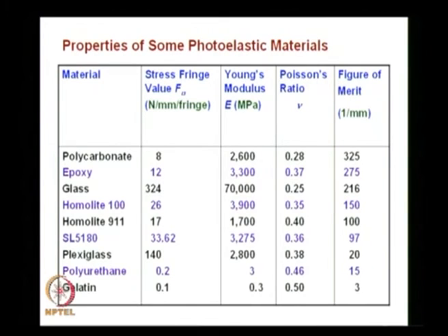So, this gives you an idea of what are the various photoelastic materials, and what we have seen in the class today was we looked at the importance of color code. We said the color code sequence is advantageous to calibrate the polariscope to find out the maximum or minimum principal stress direction, and also to find out the sign of the boundary stresses. We have looked at the nail test, we have also looked at how to find out the sign by an external member. Then we moved on to model to prototype relations.